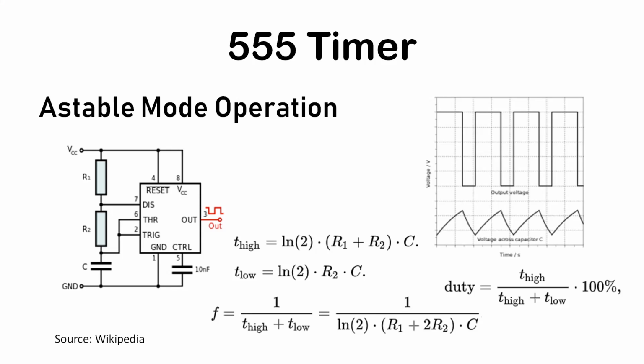Even if you leave it open, for low frequency operation the output will be okay. But when you are working at a little bit higher frequency, the output may be distorted due to the presence of unwanted oscillations inside the IC. So it is better to use this capacitor.